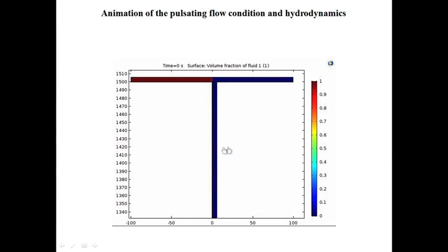This was the simulation which I previously did at the same conditions. With the known superficial velocities, we were not aware of what flow pattern could prevail in this situation at atmospheric pressure discharge. And now we are seeing here that there is a slug flow. Slug flow is occurring. The red one is for toluene, the blue one is for water.